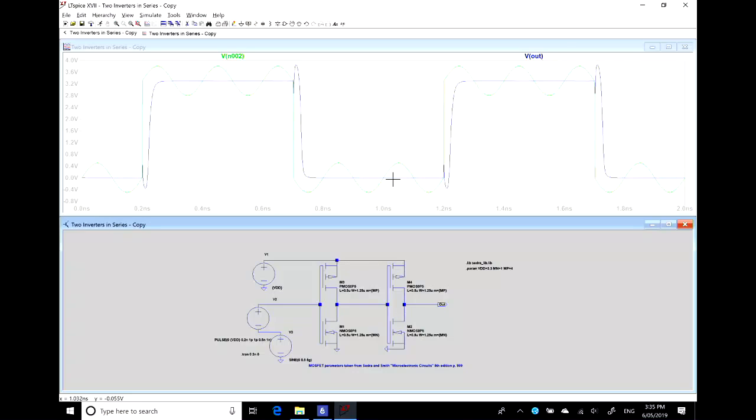So that's what we mean when we say digital circuits tidy up the signal. Noise comes in everywhere, but as soon as it goes through another logic gate, it's removed almost all of the noise. And it's because the input-output relationship is very flat, very steep gradient, very flat again.